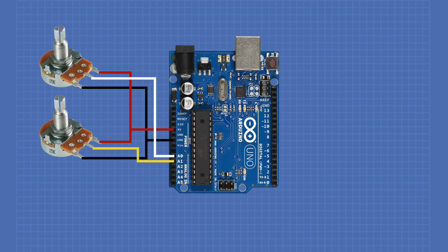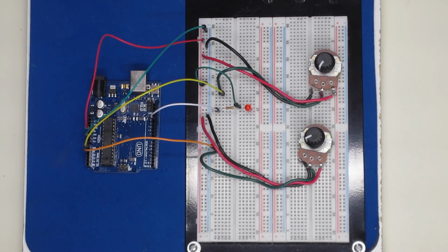And as I said, I've also wired an LED to my circuit. I've taken pin 13, fed it through a 220 ohm dropping resistor, attached that to the anode of an LED, and I've grounded the cathode. But again, you don't need to do this because there is an onboard LED. So now that you've seen how I've wired this, let's start working with XOD.